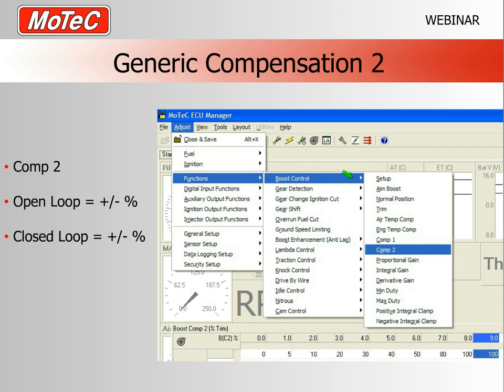This one was from a vehicle that runs a long distance off-road race, and often they will want a lot of boost initially, maybe to get past someone else, or a prologue style event where they've got to go quickly just for that amount of time. And then if they're out in front, they want to conserve the engine, they can just dial back the boost and take the load off the engine. And so this allows you to have a driver input on the amount of boost that's actually being applied.